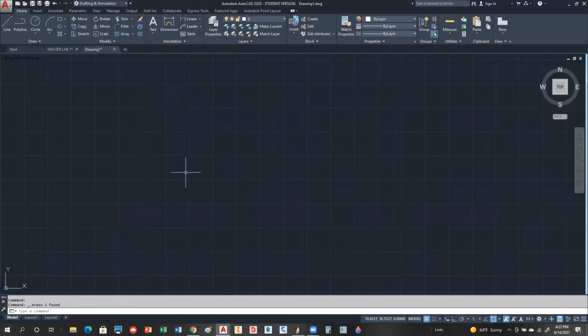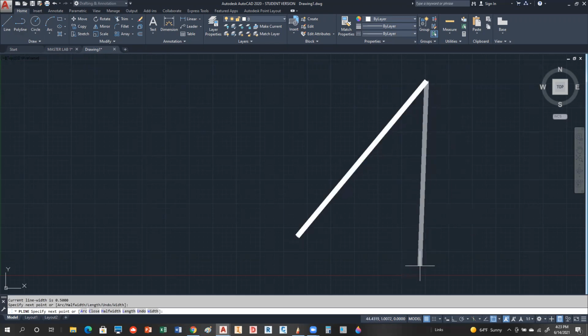So I'm going to go back into the polyline command, and I want to show you a sub option called closed, because when you generate a polyline, you can either have it open or closed, and I want to show you the difference. So I'm going to start a polyline, and I'm just going to come over here and generate it at a point, and then a point, and then a point. And I'm going to take it back to the starting point.